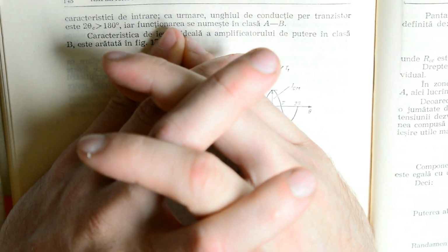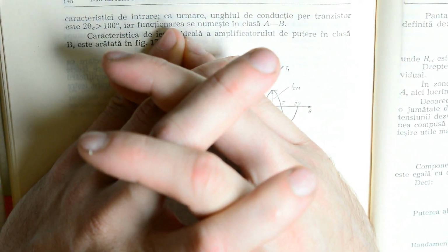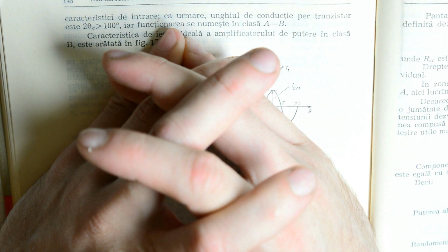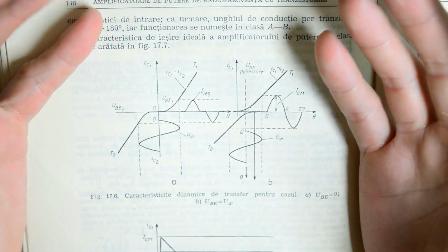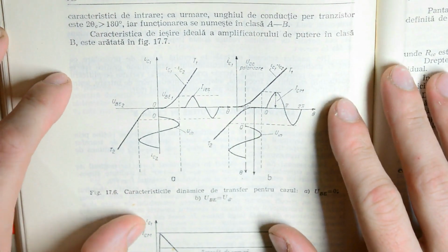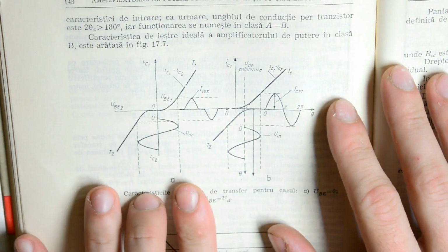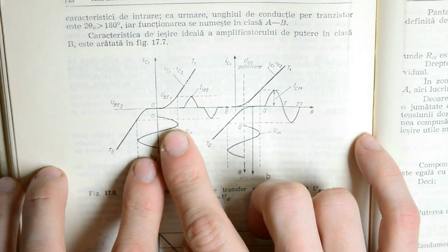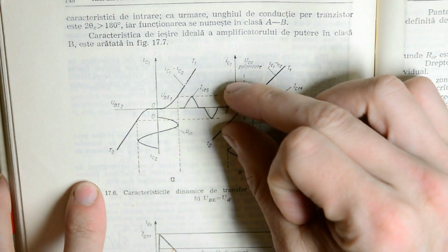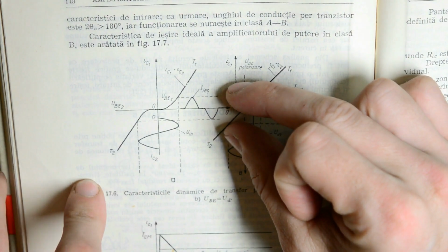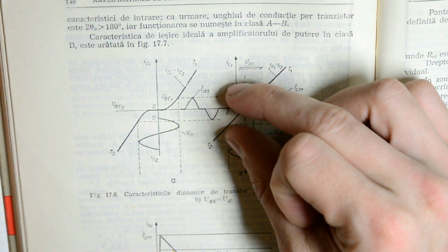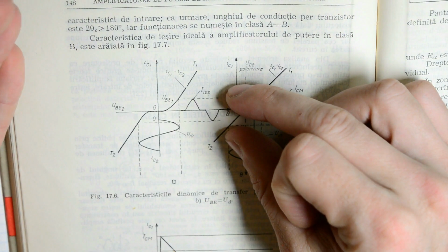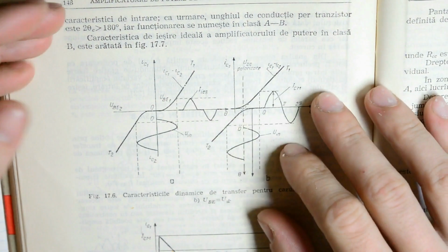Now, because the Class B chops off a bit of the signal, it doesn't sound very good. It's not a very good audio amplifier, especially if you're into high fidelity audio. So what was created was the combination of the Class A and Class B amplifiers, the Class AB amplifier. What this does is take the normal operation of our Class B amplifier, in which we took our input signal, chopped it in two, amplified it with two different transistors, and then recombined it into an output signal, and combines this operating principle with the Class A amplifier, in which the transistor is always biased, no matter what the input signal is.